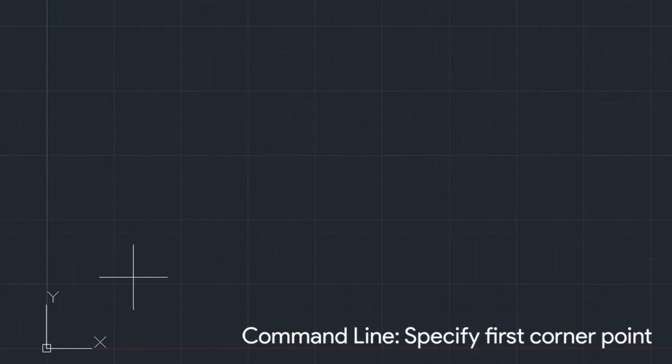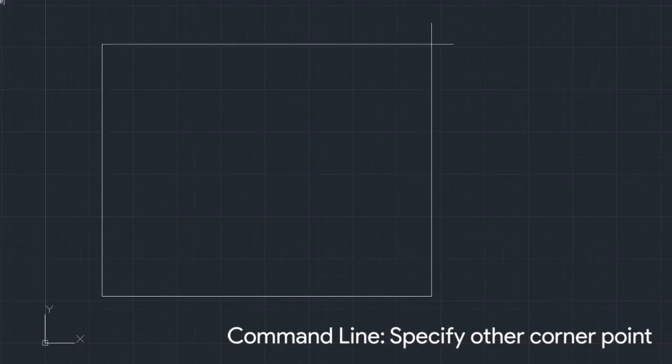So what are the steps in order for you to make a rectangle? Again, just read the command line wherein you have to specify the first corner. So now, the first edge of your rectangle is fixed at a certain point. In this case, I'm just clicking randomly, but again, you can specify its coordinates by typing, like what I said earlier. And now you are asked to specify the other corner point, in which you can again type the coordinates, or you can just click anywhere. Then there you have it.